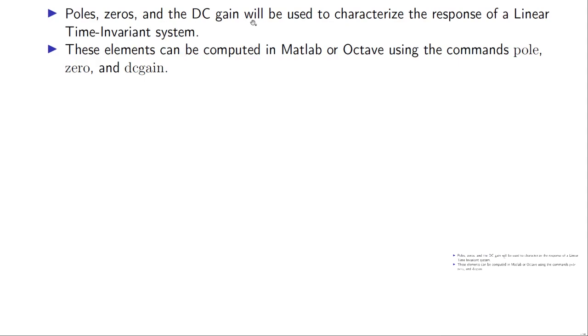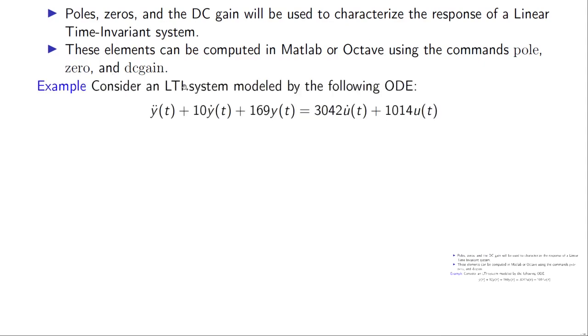These elements can be computed in MATLAB or Octave. Octave is also a free tool. You can use it online or download it, using the commands pole, zero, and dcgain. For instance, we have an example here of an LTI system modeled by the following ODE. So you have an ordinary differential equation relating the output of the system and the input of the system. The first step would be to find the transfer function.